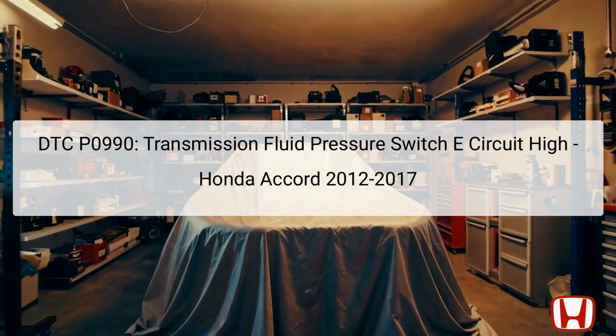The DTC P0990 refers to an issue with the transmission fluid pressure switch E, specifically for the 6th clutch circuit in 2012 to 2017 Honda Accord models. This error indicates that the pressure switch is providing a high signal, which typically suggests a lack of hydraulic pressure applied to the 6th clutch.